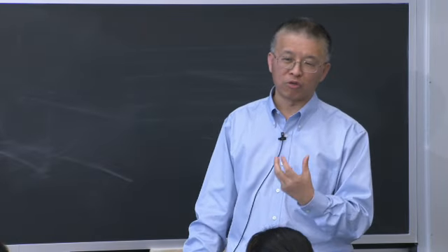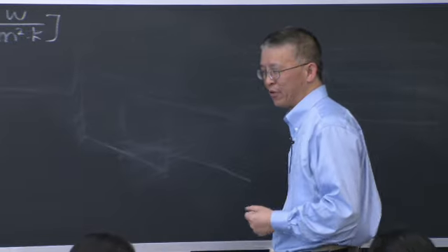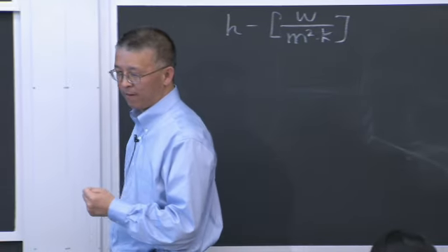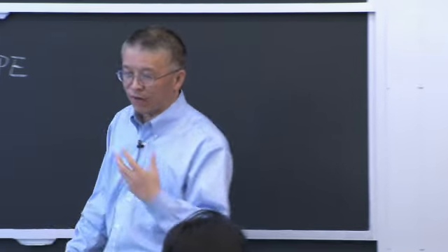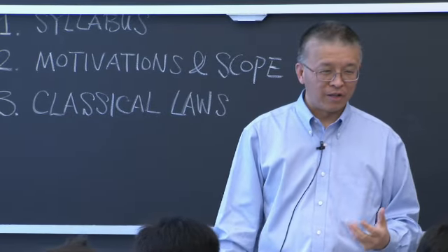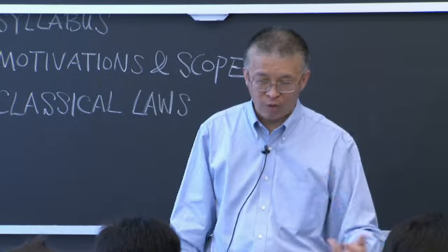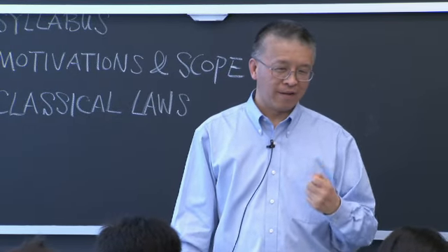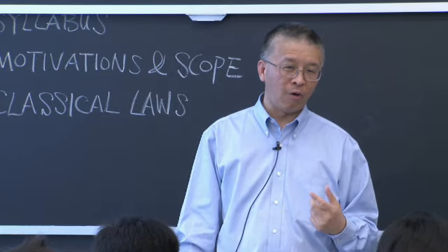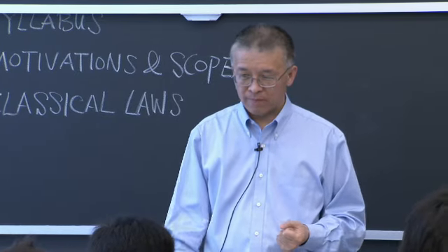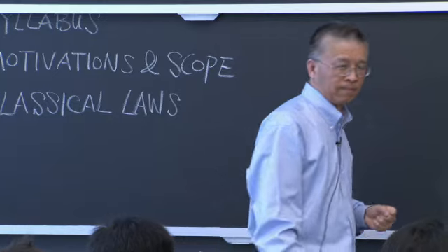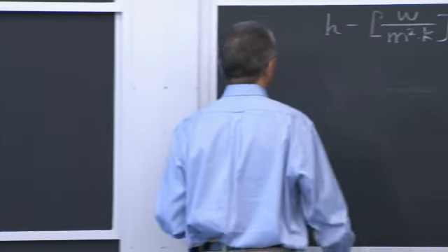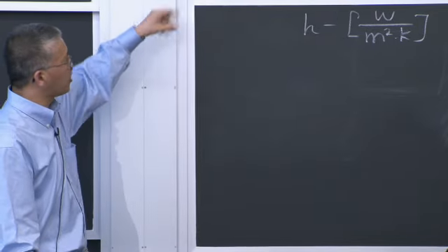That's the no-slip boundary condition, and anyone who learned fluids or heat transfer knows that. But I say that's not valid. That's not true. In fact, there's always slip. There's always velocity and temperature slip. It's just normally too small, so you can ignore it, and you will see why downstream. Okay? So conduction, convection.